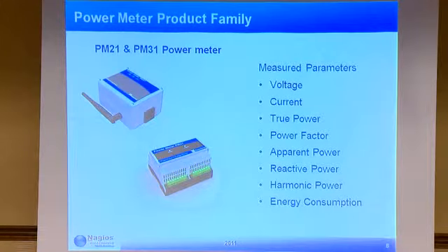When I speak of power quality parameters, in certain European countries, they have certain limitations on the power factor of the load which you're going to use. How much the current and the voltage lead and lag, whether they will be in phase or not in phase, depending upon an inductive or a capacitive load. And most computer systems use an SMPS-based power supply. It's a switching power supply, and that causes a lot of noise in the line. If you're in an educational institution or a medical organization and you have these computer systems installed, you don't want this noise going into sensitive monitoring equipment. So the power meter helps in monitoring this.